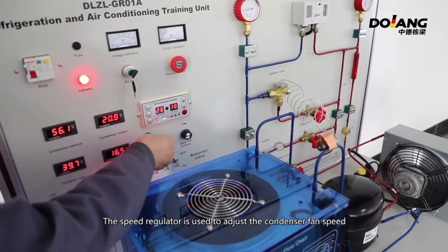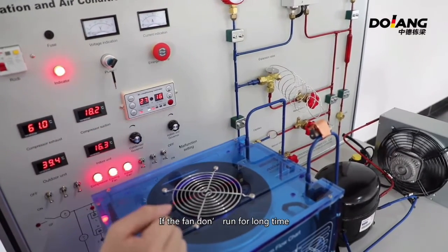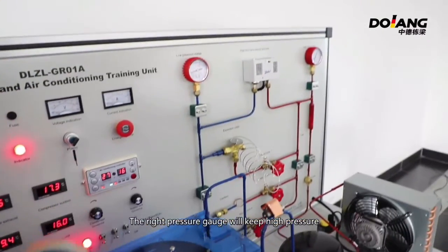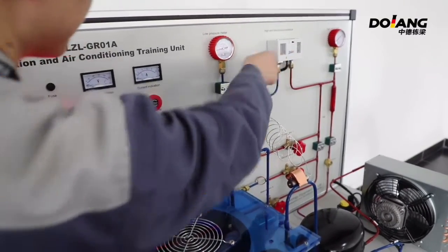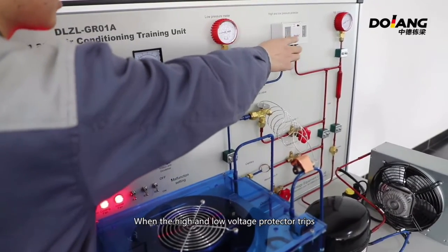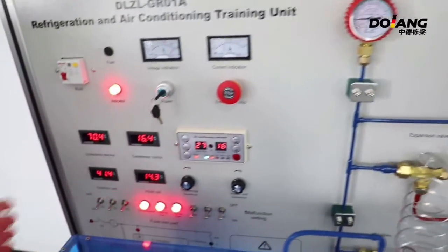The speed regulator is used to adjust the condenser fan speed. If the fan doesn't run for a long time, the right pressure gauge will keep high pressure and cause the equipment high voltage alarm. When the high and low voltage protector trips, you may press the reset button. The device may start normally.